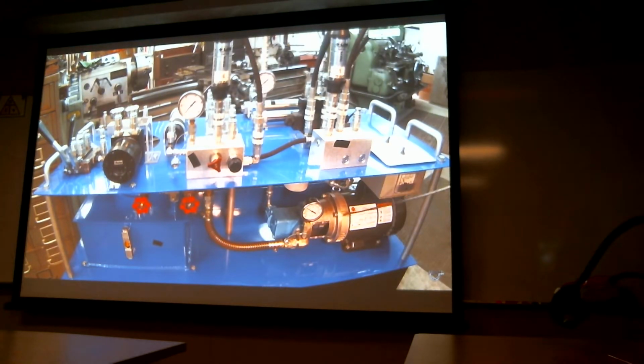Misalignment. If you misalign the shaft of this pump right here, you can pull air in through that shaft seal right there, and you can damage your pump. So misalignment is very important. Soft foot, obviously, back here on your electric motor. And then your RPM going too fast or too slow. That can affect your gallons per minute coming out of your pump. All right, that's your prime mover.